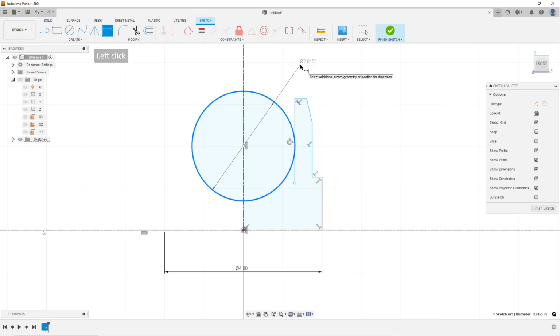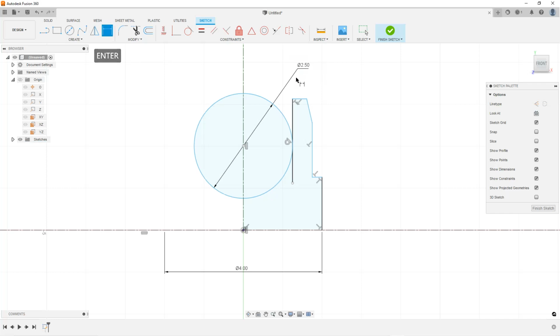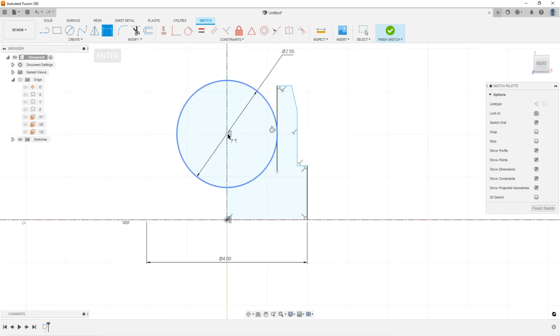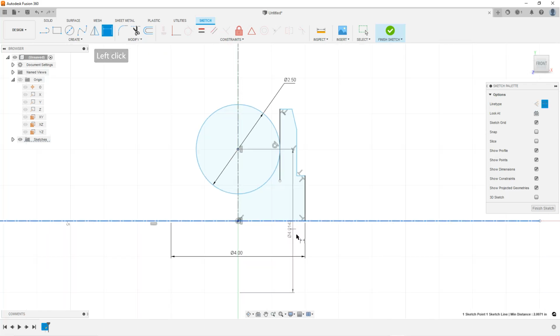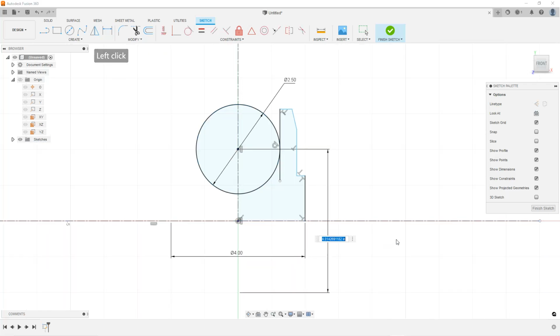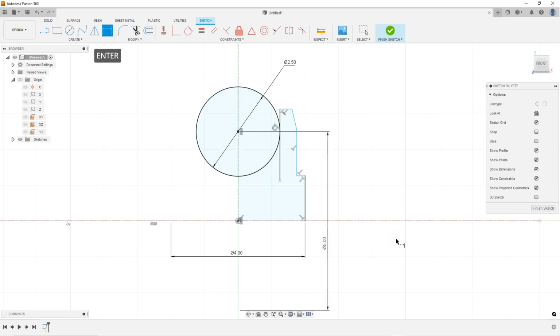that'll fully constrain things. So my inside thing here, let's make that 2.5 inch diameter, and I want to kind of lock in that circle. So let's make that 5 inches, and then I want that face where the spokes are going to come out to be a little over 1/8 of an inch. And here's a trick that I find really useful.